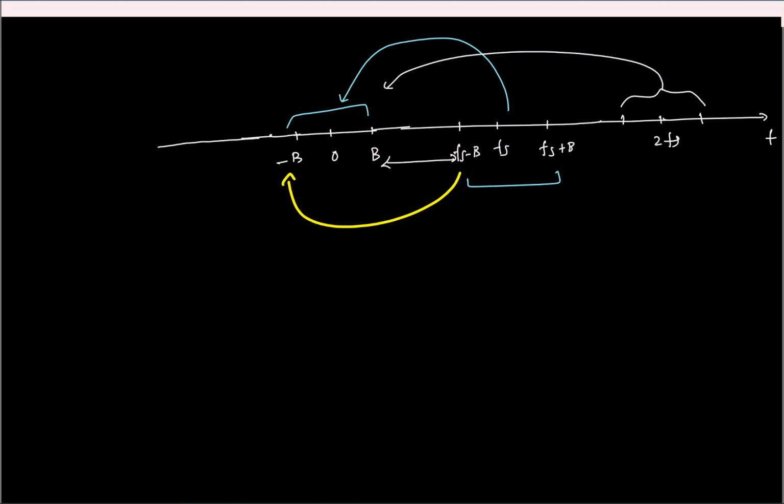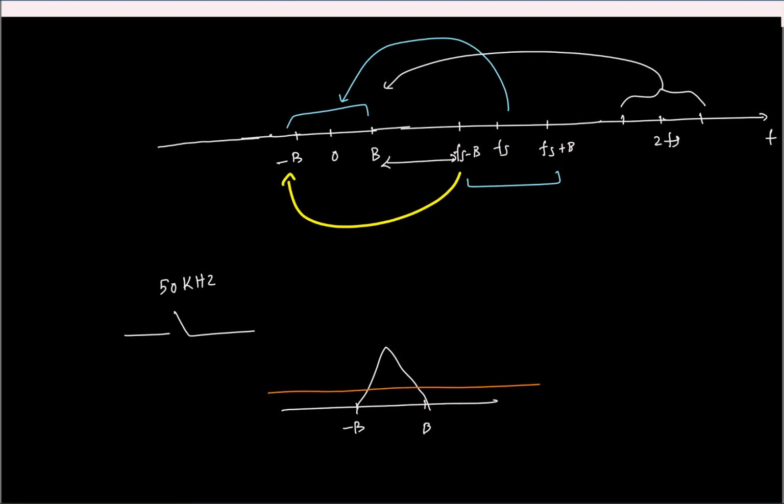So let's say when this lecture is getting recorded, we are recording basically an audio signal, right? What is the maximum frequency or bandwidth of an audio signal? Let's say 20-24 kilohertz. So let's say we obey the Nyquist condition and sample it at say 50 kilohertz. If I directly take the signal and sample it, will it work or do you foresee any issues? Yeah, we just saw, right? Your signal might be band limited to the required bandwidth. But when you're sampling the signal, it is not just the signal alone. You will have all sorts of stray signals. If not, you will have electronic thermal noise, which is omnipresent at all frequencies for us.